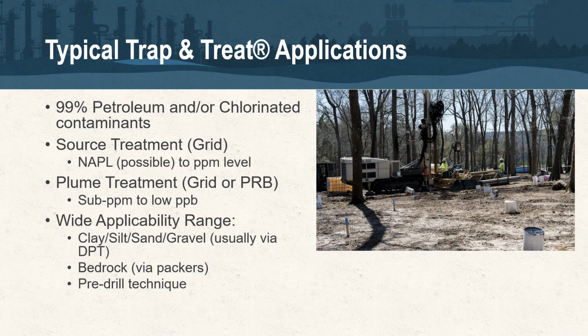A lot of times here, we do implement grid where we go in and grid out the whole treatment area, or we install a lot of reactive barrier walls. One of the spring webinars that I gave was focused on PRBs. If you're interested to learn a little bit more about that, that recording is on the RPI website. And we've been able to achieve MCL level criteria, low ppb criteria using these technologies.